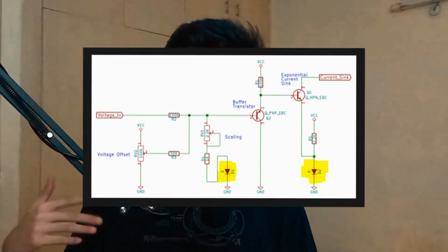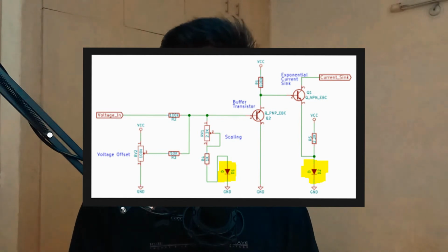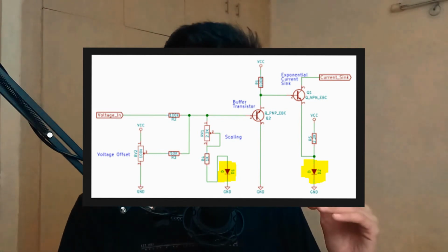Now, the original Rene Schmitz design used a bipolar supply. What Elliot Williams did was he modified it so that the same circuit would work, especially the exponential converter, with the single pole supply, and he achieved that by adding just 2 diodes as offset voltages. This oscillator is basically a sawtooth core oscillator.